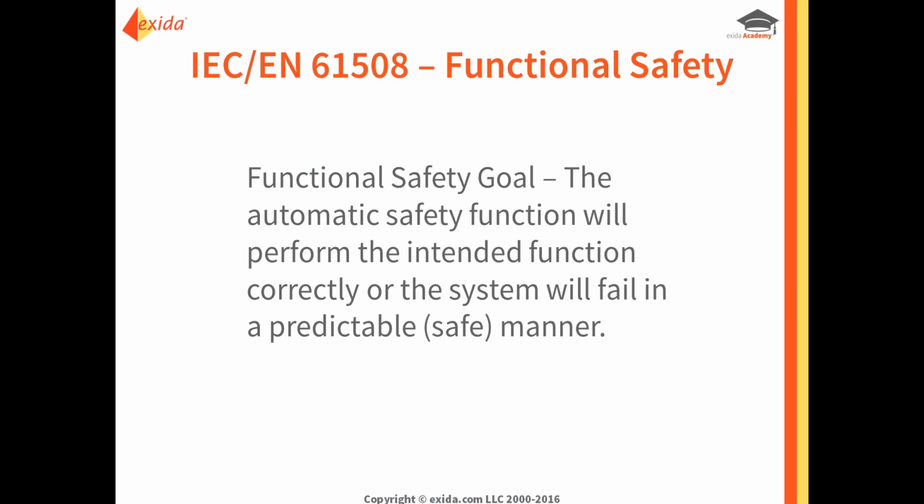When we are talking about functional safety of a valve, if it's a close-on-trip application, we want that valve to close when it is called into need. When everything else has gone wrong, they need to shut the process down and do it quickly. That valve needs to be able to do that or have the system fail in a safe manner.